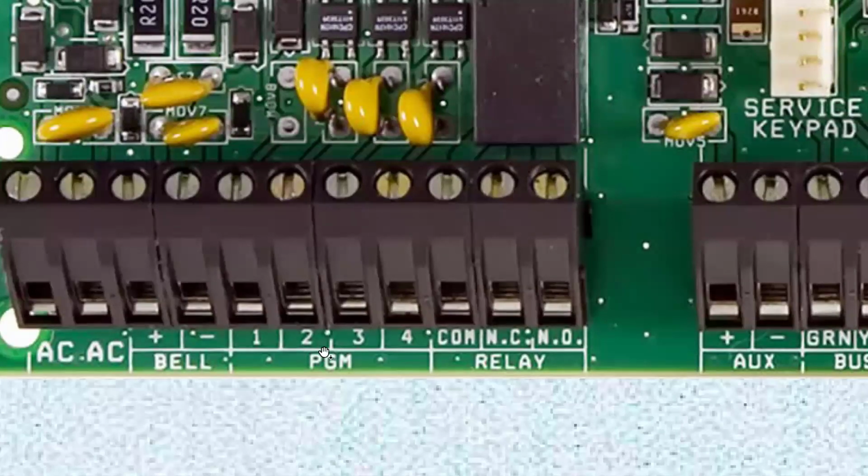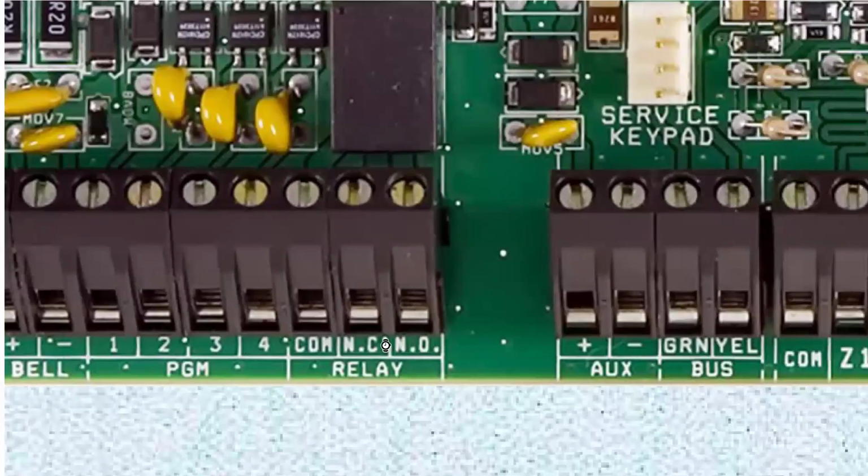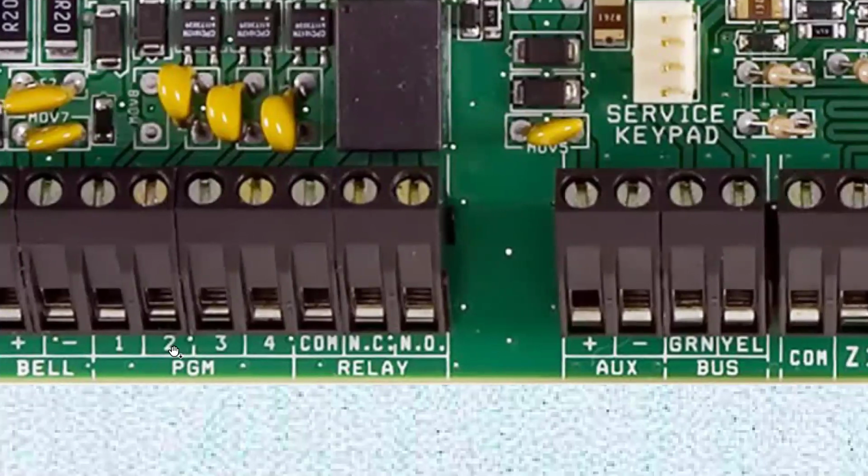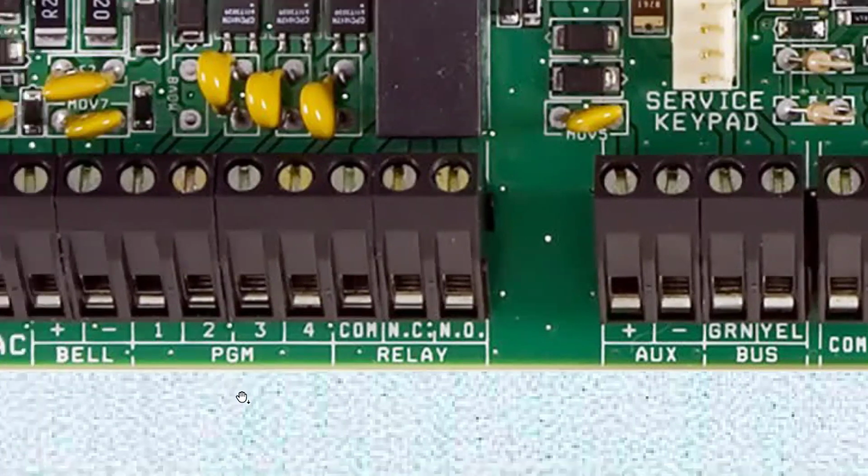All right. How these work, they are pretty much floating in the air. And I think these ones here, if activated, get connected straight to ground. So some of them are connected to ground, and the other cable has to be connected to the positive side of the auxiliary here. Or some of them are going to be connected to positive, and you're going to get the other wire connected to the common. Different companies produce it different ways. You've got to familiarize yourself with how this particular board works.